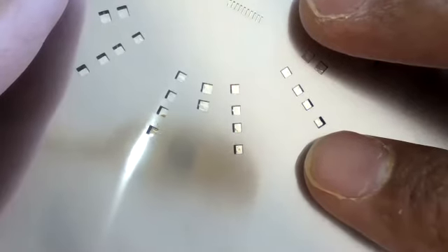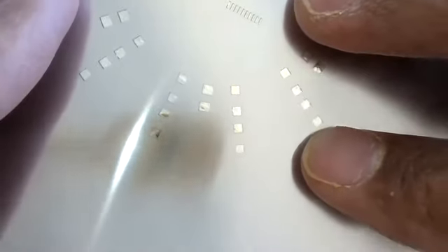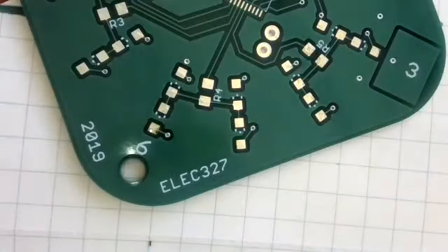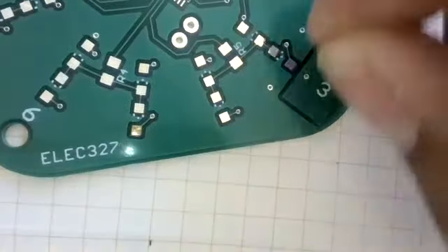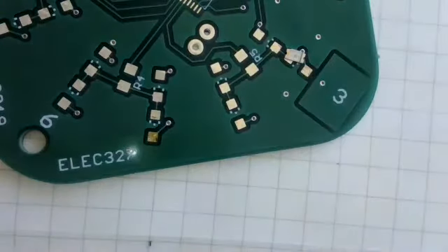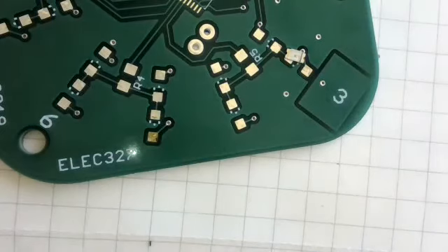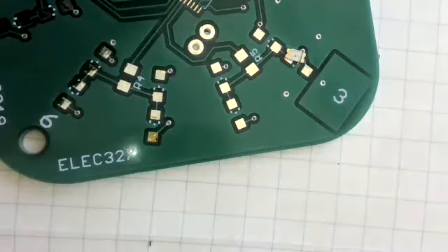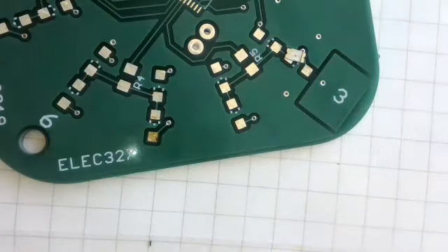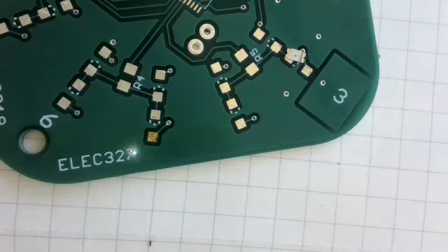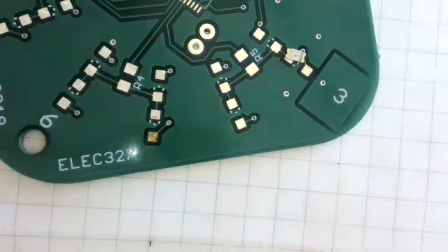But the idea will be that you line everything up really nicely, and then you scrape some solder on top, and then you very carefully unpeel it like this, and then with tweezers you put all of your LEDs on the LED spots, and you put resistors on the resistor spots, and then you put it in the oven, and then you cook it, and everything melts, and then you end up with a beautiful functional printed circuit board that you then can proceed to do the rest of the lab with.